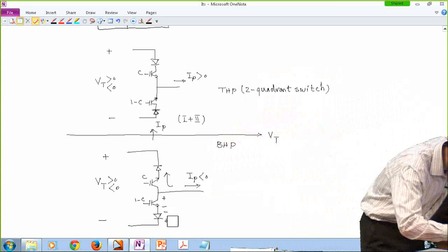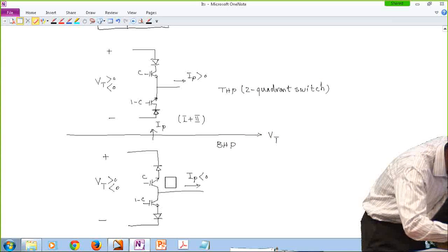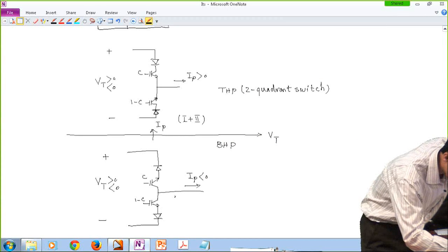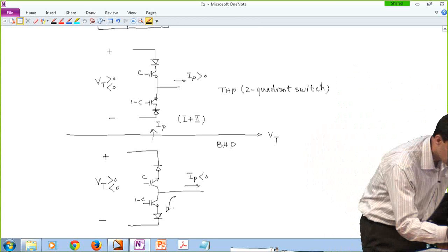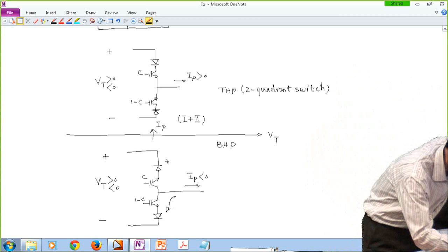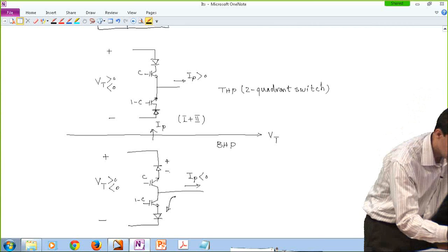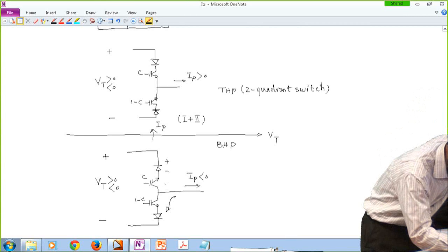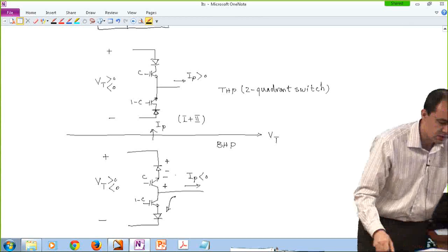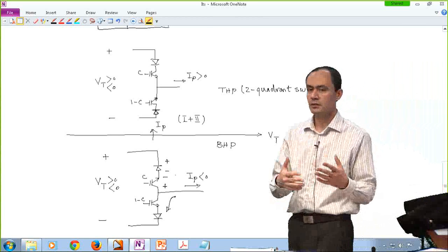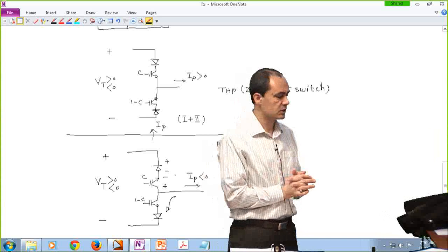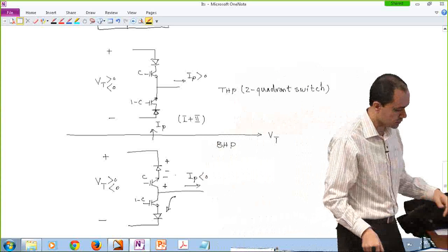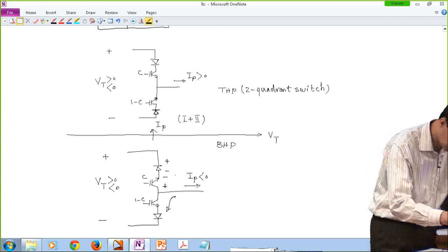And in case we have current going through the bottom throw, or the bottom throw is basically shorted, and the voltage is positive, then the diode is blocking the voltage. If it is negative, then the transistor is blocking the voltage. Again, we have two elements kind of back to back. Doesn't matter what the polarity of the voltage is, it's actually going to be able to block that voltage.